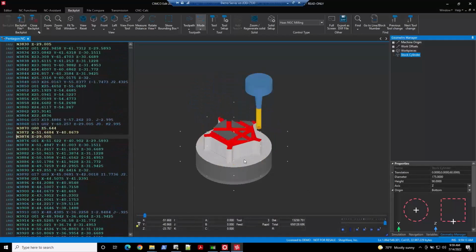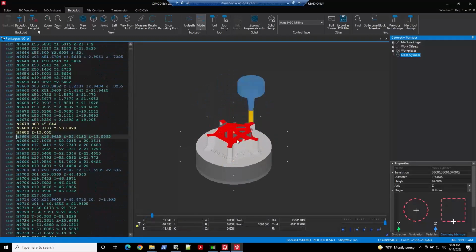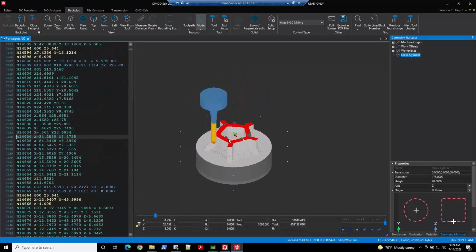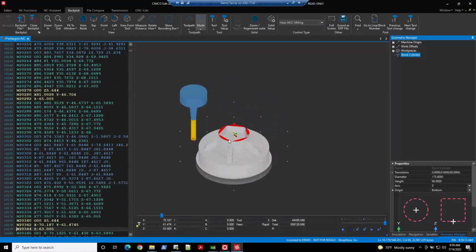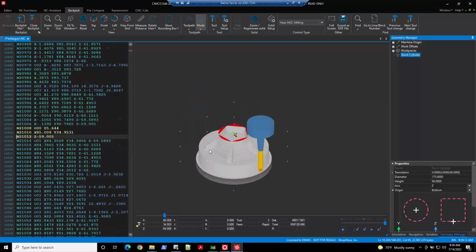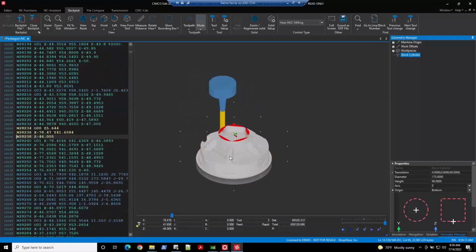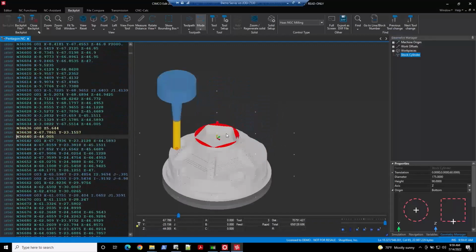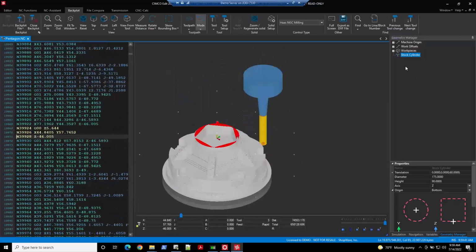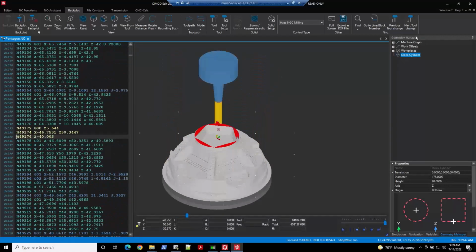you can see that we're going to get a red marking on the file because it's actually gouging what the stock part is actually cutting inside of here. So very similar to Mastercam, you're going to get a good gauge of where we're overcutting, where we're undercutting on these features inside of here. So right off the bat, if you get that red inside of the window here, you're going to know that, oh, maybe I need to adjust my stock back to what I had before.